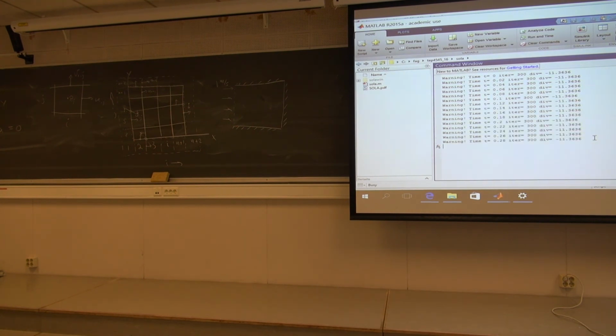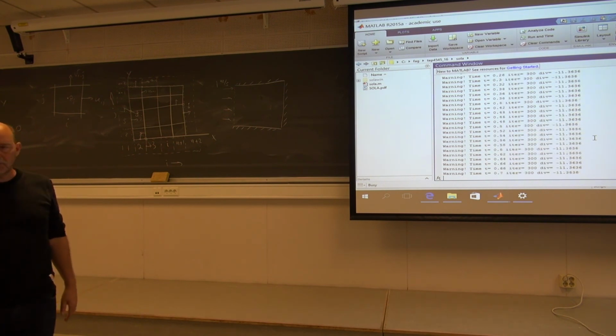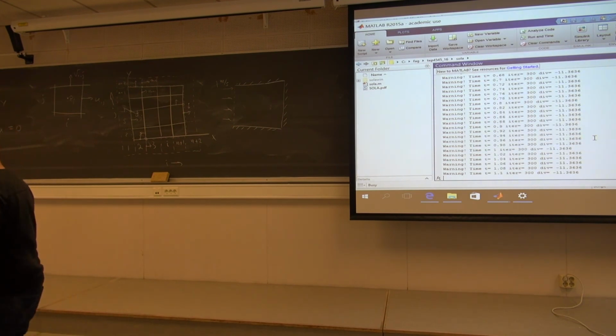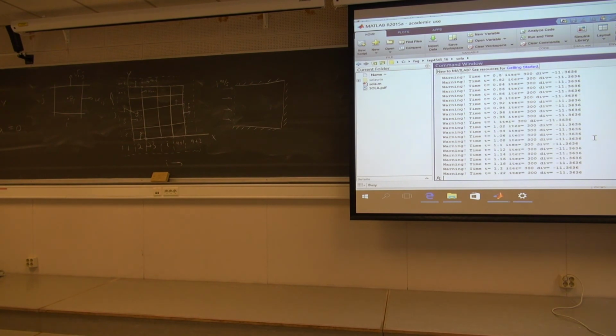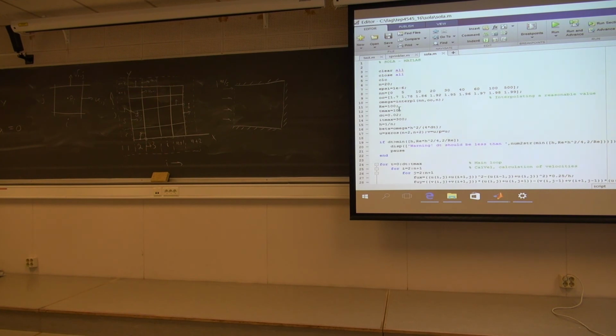He's struggling. And you can tell he's struggling. He uses 300 pressure iterations for every time step. That's the maximum allowed of the pressure iterations, trying to solve this Poisson equation. It's not possible. And you see the divergence is totally bananas. But he doesn't crash, strangely enough. Let us crash him and say we don't have to simulate until time t equals 10. We can just simulate 1, just to have a look.